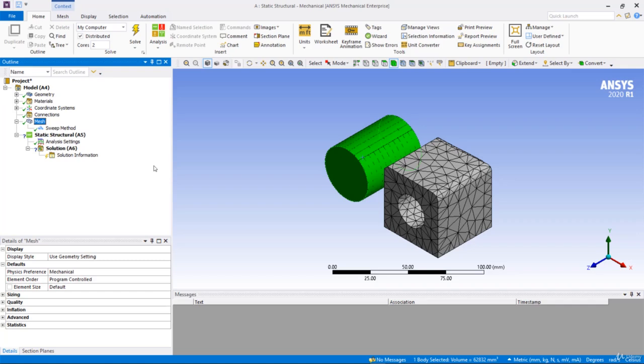And remember, the sweep meshing technique can be applied to generate hexahedral elements on a few of the objects, especially when you are using mechanical pins to join two objects in an assembly structure. There might be some critical areas where you use this sweepable mesh technique and create hexahedrons on that pin and on that contact area also. In such cases, this particular sweep mesh can be applicable.